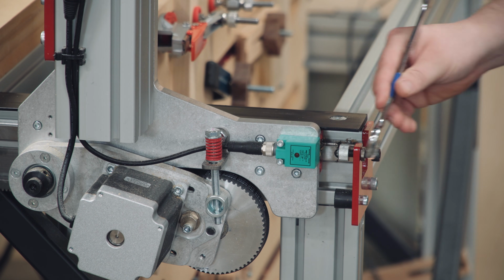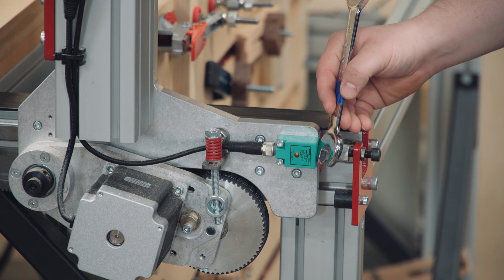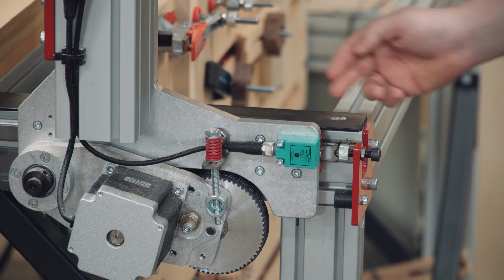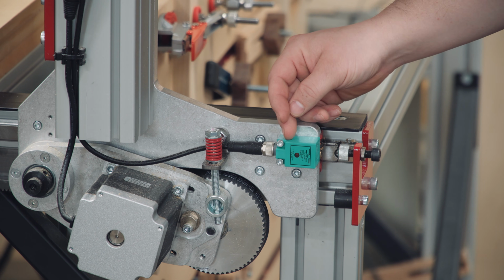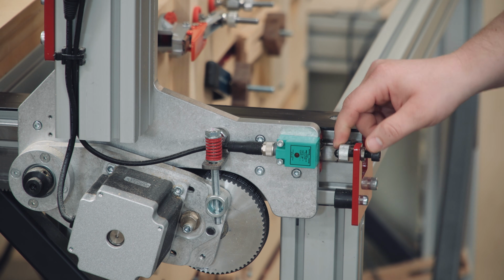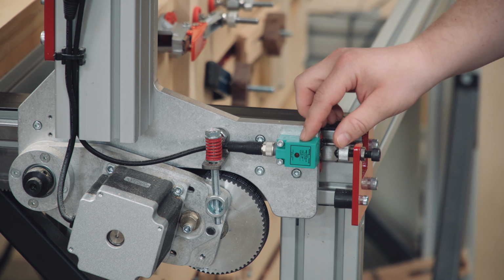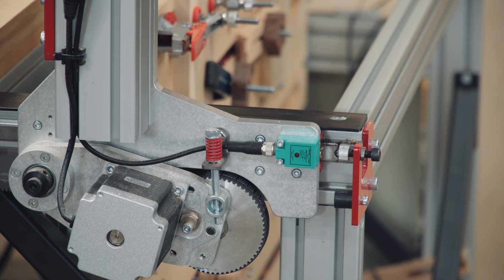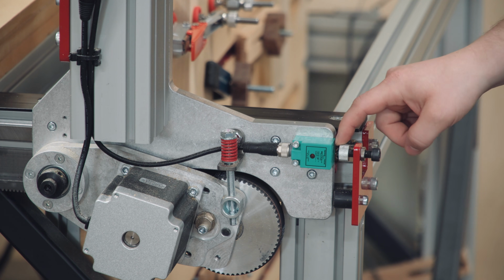So if I put a piece of metal here, you'll see that light go off, right? So that means the switch is being tripped. And during the homing process, it moves this Y-axis closer and closer and closer to this piece of metal, which is calibrated so that it knows exactly where it is in physical space. So let me press the home axis button, and you'll see that limit switch be tripped as the machine comes this way. So it was tripped, and there's a little bit of a gap here.